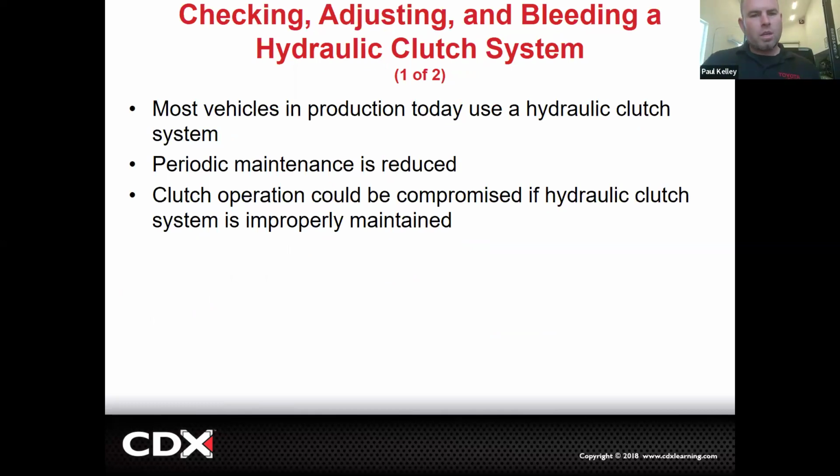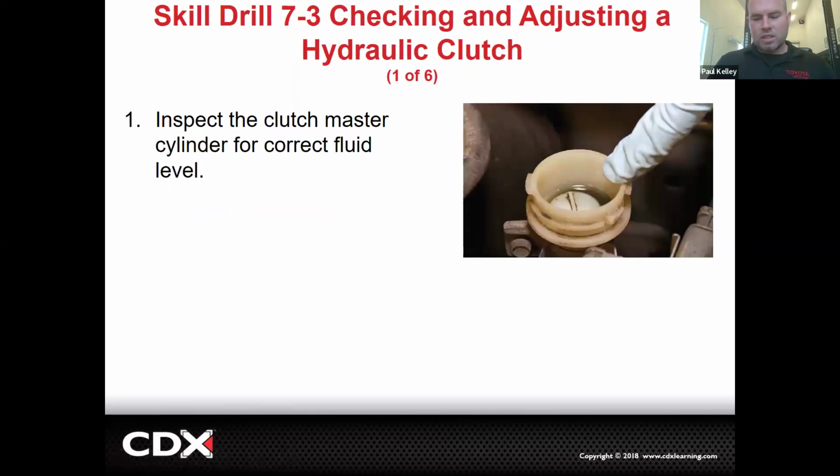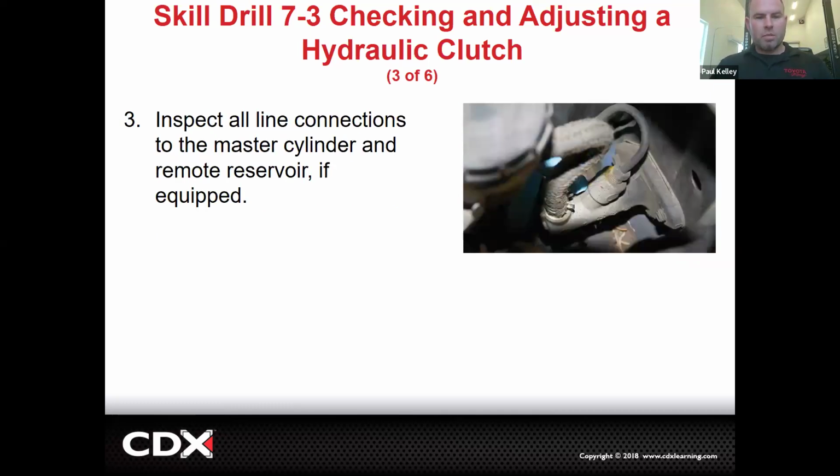Cool. Inspecting. Now bleeding, this one is kind of a hassle, but the bleeding can vary from one vehicle to the next. Old fluid causes issues. Brake fluid is hygroscopic. Remember, it absorbs water. So we can test it the same way we test brake fluid with strips, or with an electronic tester, and check the fluid level. This is using the tester to tell if it's any good, check the boiling point and whatnot.